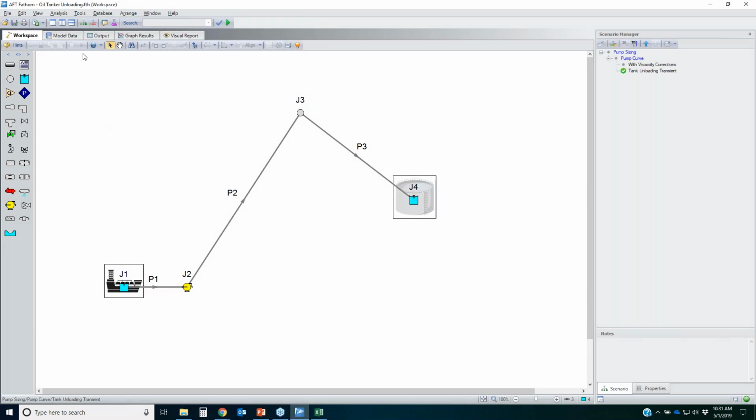The next thing that you would do is under the analysis menu, you go to time simulation. You could simply do steady state only or transient. Let's say that you did a transient simulation, but then you want to go back to doing just a very simple steady state run. You don't have to turn off the add-on module, nor do you have to delete all the transient data that you specified. Simply change it to steady state only, and you can do a simple steady state run.